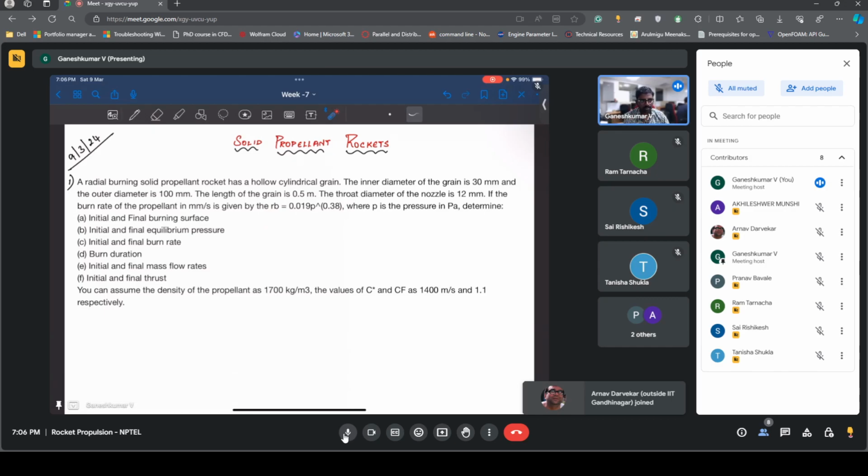You can even model it using an advanced CFD based model, but people haven't been successful using modeling techniques. Basically this is the characteristic of the burning behavior of a propellant. It is coming from experiments, and it is going to depend on pressure.